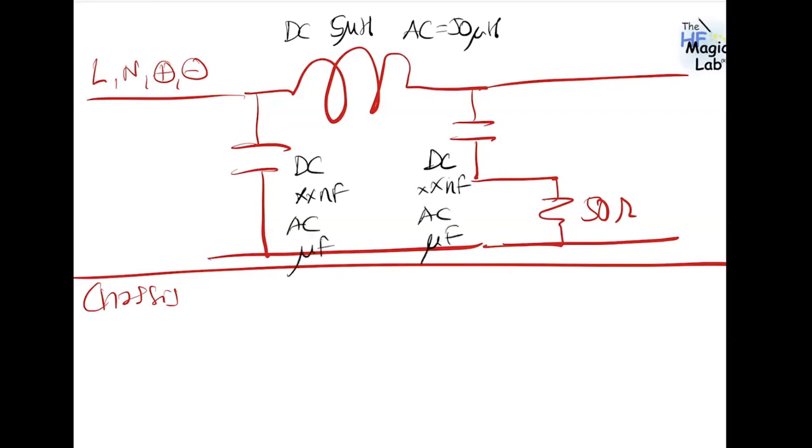So basically what you are trying to do is represent the impedance that was agreed for the different applications. The inductance value differs because of the typical length of cables. This is trying to represent the real world, but obviously it is not able to match every circumstance. Something important in the AC situation is that if you don't have a specific ground system for your LISN, you will need an isolation transformer, because these microfarad capacitors will be connected from line to earth and from neutral to earth.